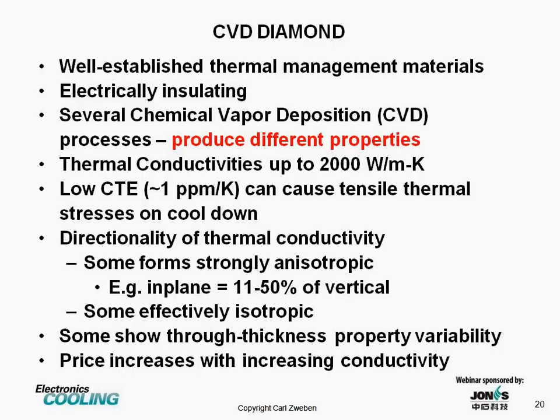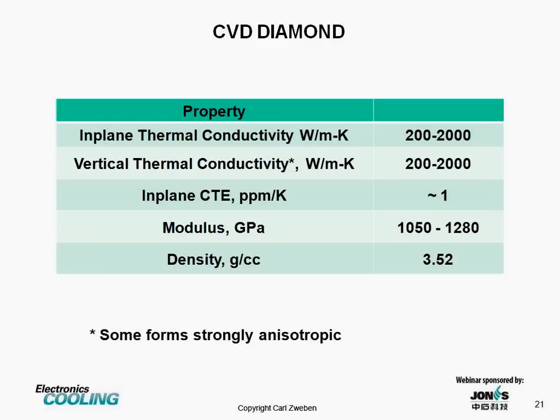Properties can vary significantly. In addition to the anisotropy, some forms of CVD diamond show through thickness property variability. And an important issue to consider is that price increases with increasing thermal conductivity. So you want to have a good idea of what you really need in your application so you don't overpay.